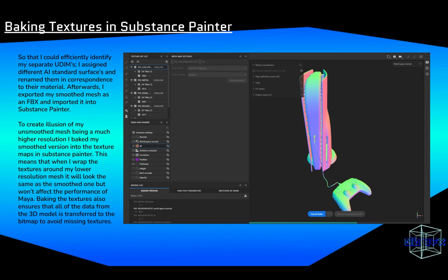To create the illusion of my unsmooth mesh being a much higher resolution, I baked my smooth version into the texture maps in Substance Painter. This means that when I wrap the textures around my lower resolution mesh, it will look the same as the smooth one, but won't affect the performance of Maya. Baking the textures also ensures that all of the data from the 3D model is transferred to the bitmap to avoid any missing textures.